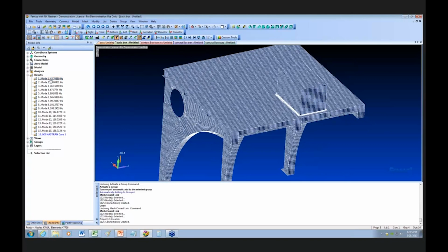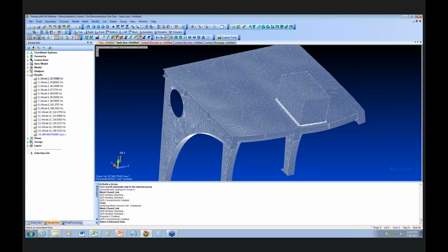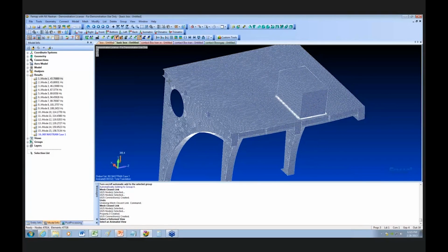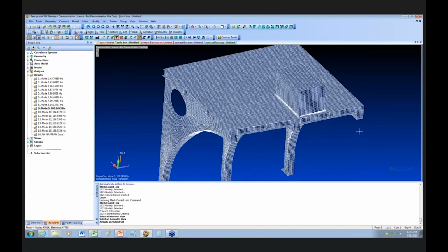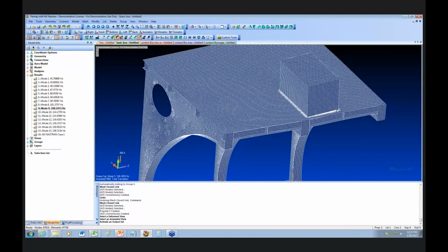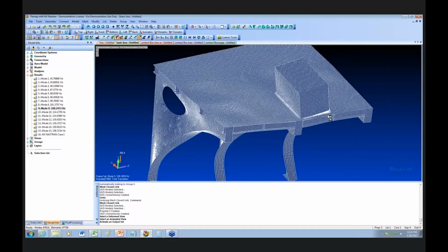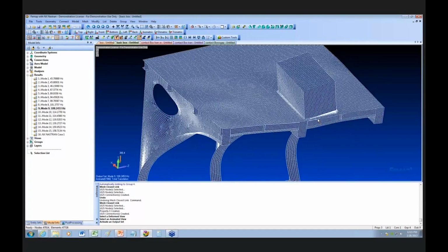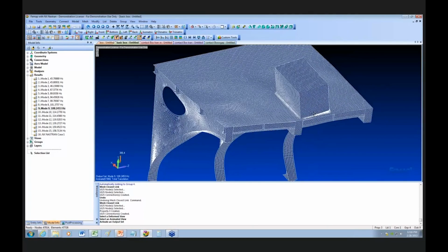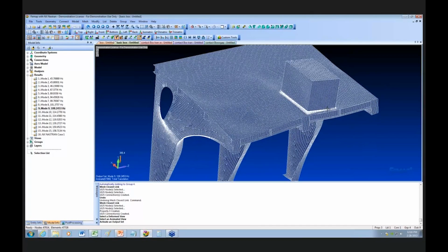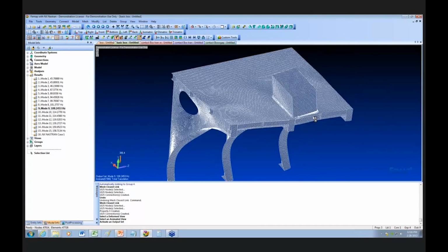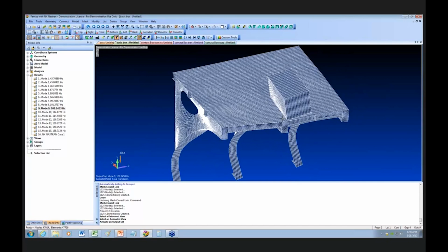I ran a normal mode right here, okay? And I can come in here and actually animate this. I can go through these, and I can see that there's a little interaction going on. I didn't see this before, but if I looked at this further, I would stiffen these springs up so it would couple this together, and I wouldn't see this interaction that's going on right here.